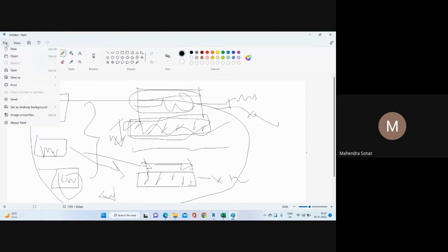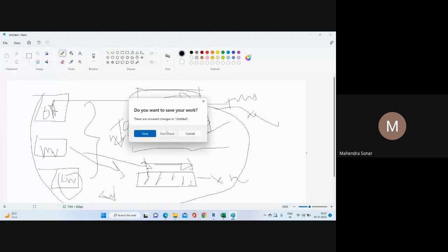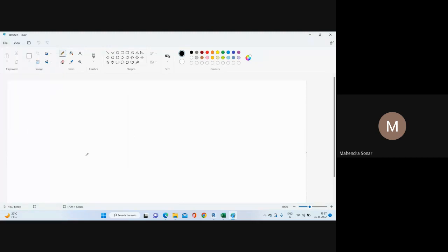So what we'll need to do is set your point. You can say the survey point or project point here. If you open your Revit window and turn on this point, you can see it. This point is your x equal to 0 and y equal to 0, and z you can give any level. X means your x, then y location, and then z is your third dimension.